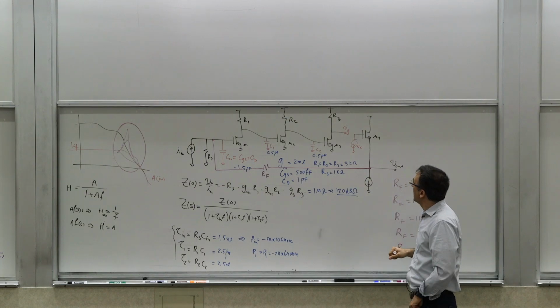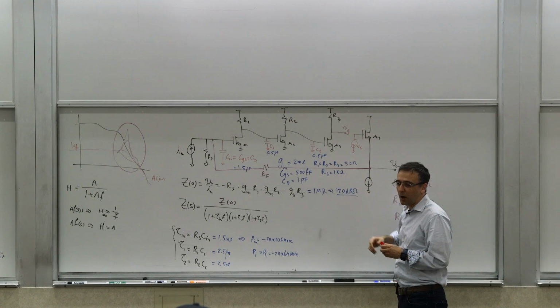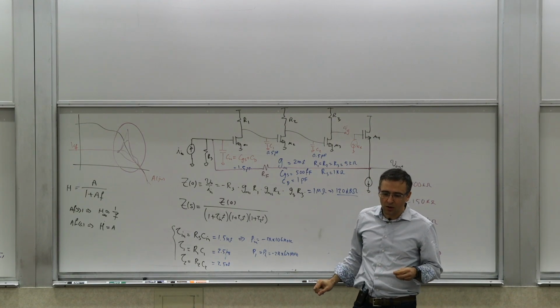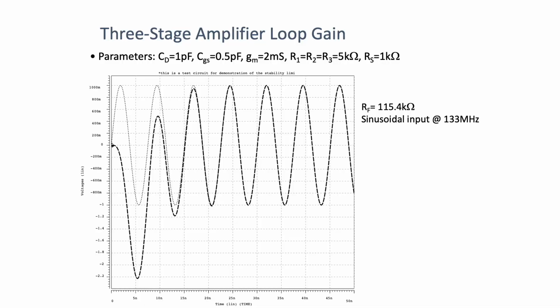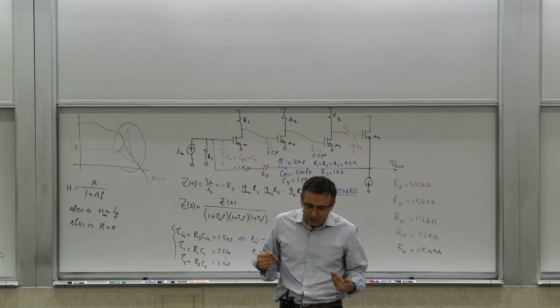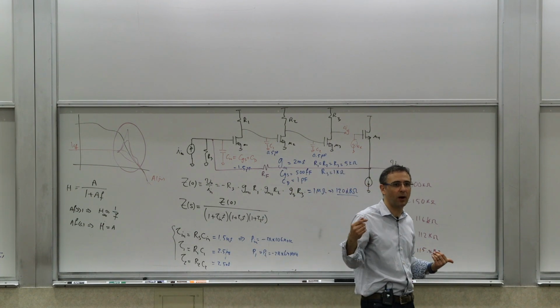And so, if you apply a Vx and look at Vy, what comes back? Looking at it in simulations, you see that after the initial transient, as the capacitors need to charge, they're identical. So around that voltage where you get something that neither grows nor decays, your loop gain is the negative of this quantity, right? By definition, it is negative Vy over Vx.